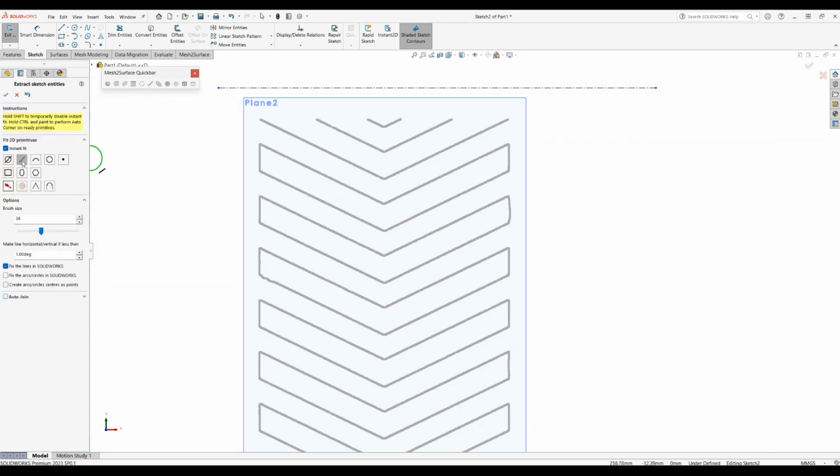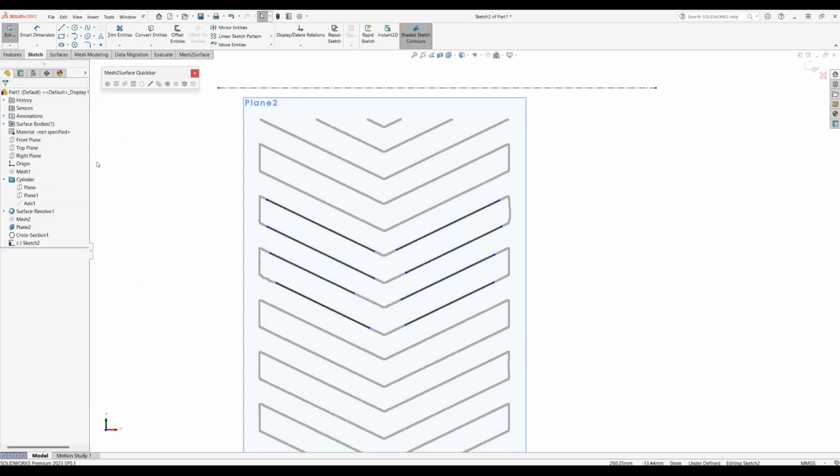We'll make sure that I have pre-selected the line, and then I simply hold my left mouse button down so the software can extract this information from the underlying scan data. For the purposes of demonstration, I will extract several, so you can get the different angles and probably get the average out of it. Once I'm ready, I will fix the lines in SOLIDWORKS so they don't move accidentally, and press OK.